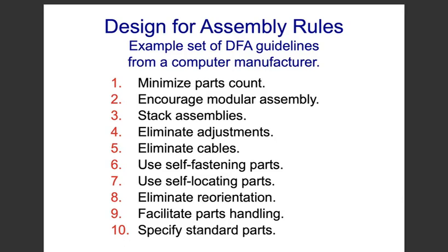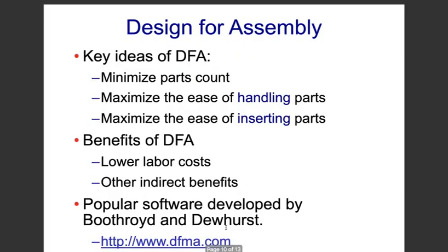Again, guys, standardization. So the key ideas of DFA and DFM: minimize part count, maximize the ease of handling parts, and maximize the ease of inserting parts. I think these three points are quite related to what you have learned from time and motion study. You learned micro motions and you also learned macro motions.